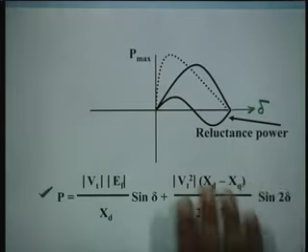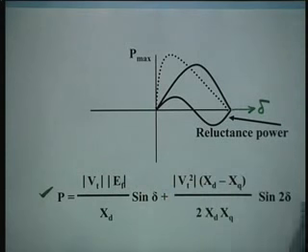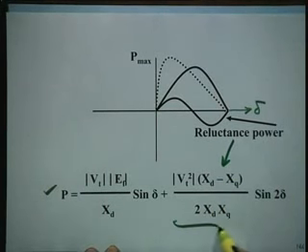Now, we have seen here the phasor diagram for the salient pole machine, and that I have already explained to you. Let us now go for the power angle curve for the salient pole machine. As you can see, this part was known to us for a cylindrical rotor, and this part is called reluctance power, which is a second order term. That means there has to be more power in a salient pole machine, and so the maximum also shifts slightly less than 90 degrees. All right.